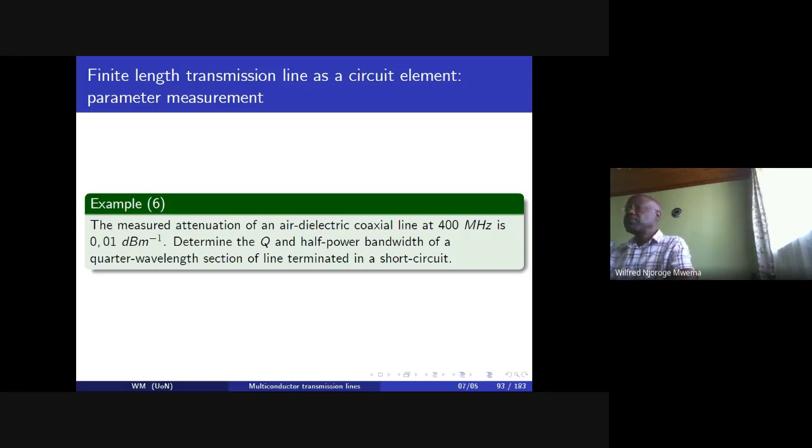So in practice, at given intervals of the line, we put very thin discs of dielectric to anchor. It's more like we're putting anchors or pillars along the line to try and make sure that the line separation does not change. If the discs are thin enough, then the effective dielectric constant will be that of air, so to speak.